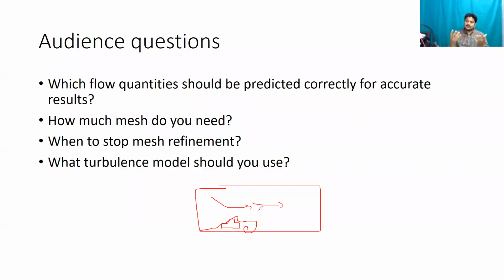It doesn't matter what is the system. So there's the boundary layer component, and there is the outside boundary layer component, right? And then there's something called as free stream, where the velocity is just following a boundary condition. It is not at all affected by your object, correct? Even in your wind tunnel, really far away from the car, you're not going to be affected. But as you get closer to the car, you're going to get affected by the shape of the car, right? That is exactly what aerodynamics is.